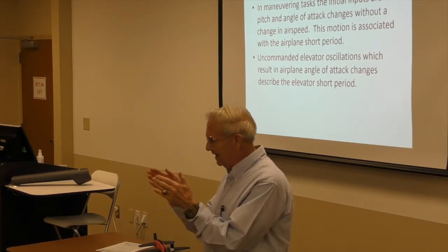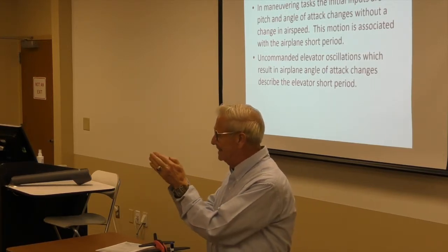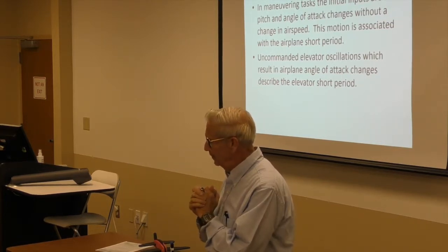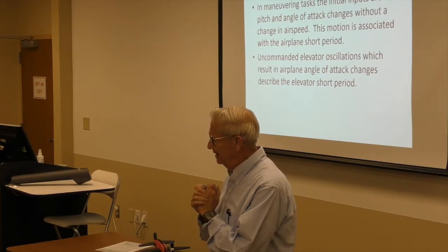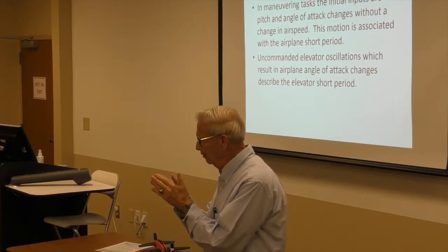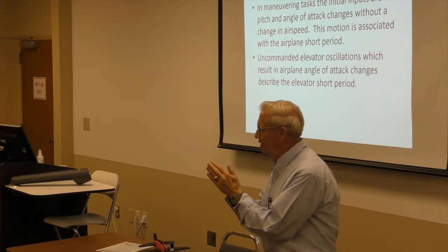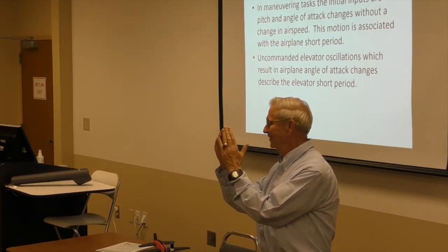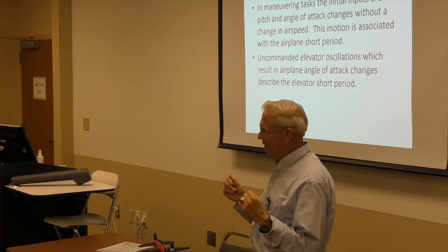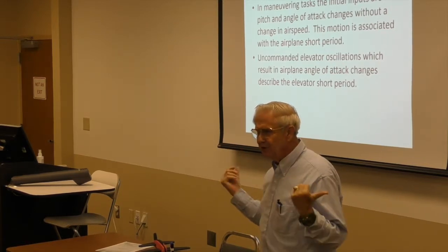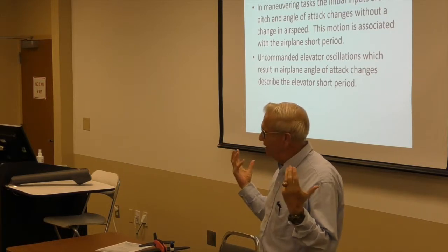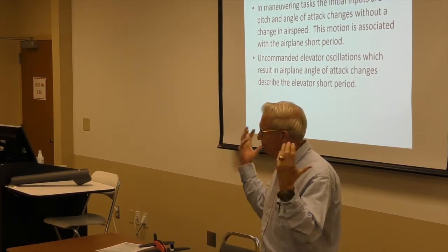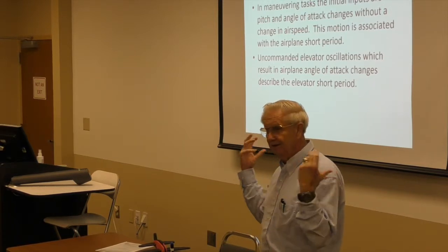and what caused the problem with this airplane was that you don't want to design an airplane with curved control surfaces. The 99's elevators were curved. And the trouble is, when you build them, one side will get bigger than the other, okay? And what would happen, particularly if the leading edge was contaminated with ice, or actually the way we were testing, we'd inflate the de-ice boots on the horizontal tail.